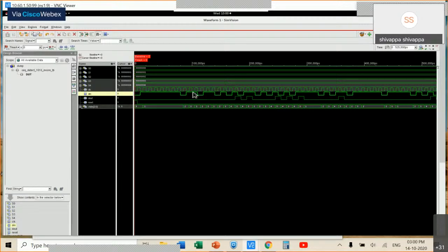And here if we consider from here 1010, right? No. So if you look at here 1, it is considered from here. Okay, 1, 0, 1, 0, and then it has given output here. Okay, and then 1, 0, 1 here because it's overlapping, it has given output here. So that way, actually, you can play around with the stimulus.